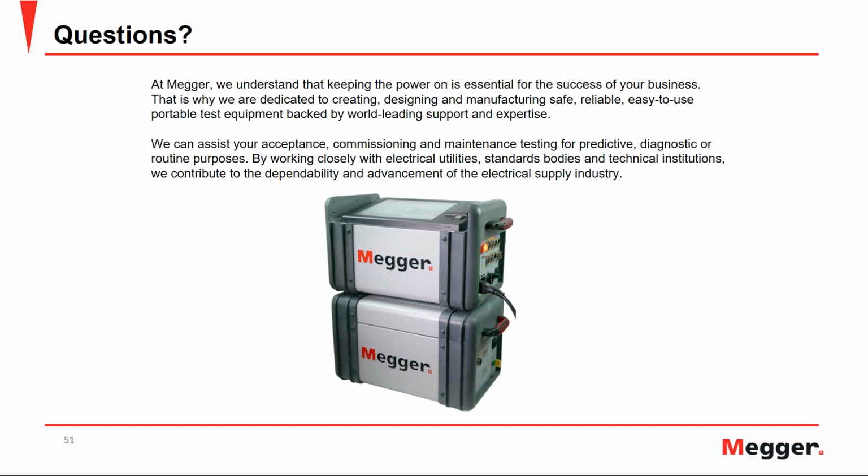When you run into those kinds of cases, one thing you need to remember is that anytime your power factor values improve by themselves, let's say it was 0.5%, and then you test today around the same temperature and it comes out 0.3%, that's something that needs to be investigated. It's not a good thing. Likewise, when you get a negative power factor, that is something that needs some investigation.